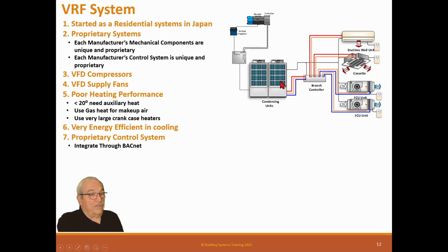So I said, okay, good, not a problem. So we built it, and when I got there, I learned that the points inside of VRF doesn't look like any points inside of our systems. So the word seamless integration, not so much. It turned out all we could actually do is stop the system, enable it, disable it, and reset the temperature set points in the space. That's it. We could see a few alarms, whatever, but that's all the points it had.